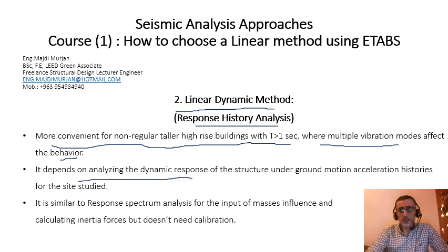It depends on analyzing the dynamic response under real recorded acceleration at the site studied. It is similar to response spectrum analysis for the input of masses and calculating the response.